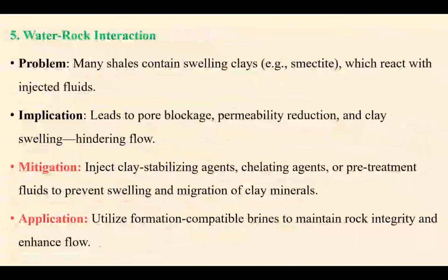Now, water-rock interaction. Many shales contain clay. Clay swells in the presence of water and reacts with the injected fluid, that is water, and then there is hydration of the clay and swelling of clay. They have a detrimental effect on recovery because of the pore blockage, permeability reduction and clay swelling. So ultimately it hinders the flow.